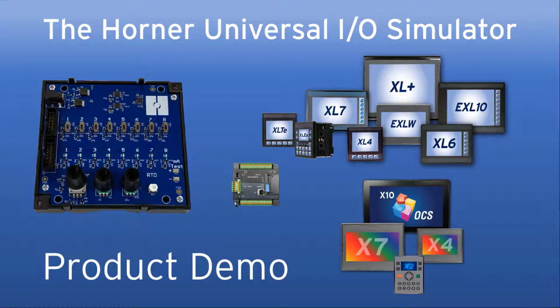I have another question from another John asking if it can handle high voltage as well as low voltage digital outputs or just dry contacts. So, from a digital I/O standpoint, the outputs from the simulator are effectively just 24 volts based on the position of the slide switch. And then the simulated outputs are just 24 volt outputs from the controller into the simulator to light up the LED. So there's nothing high voltage there. It's all pretty much 24 volts DC, both in and out. Couple good questions there. And if anybody has any additional questions at the end, we'll make sure we cover those as well.